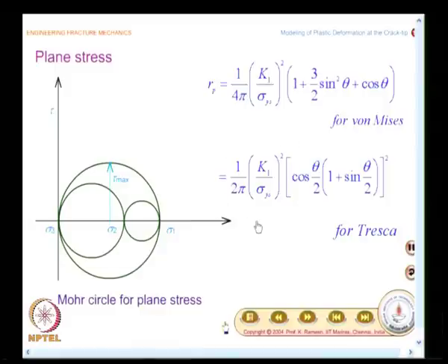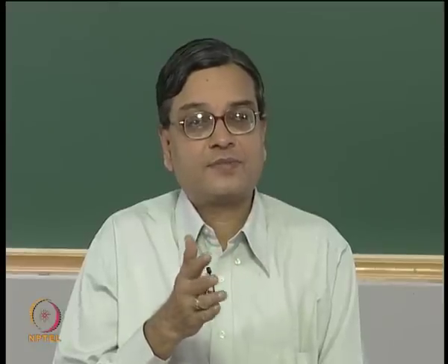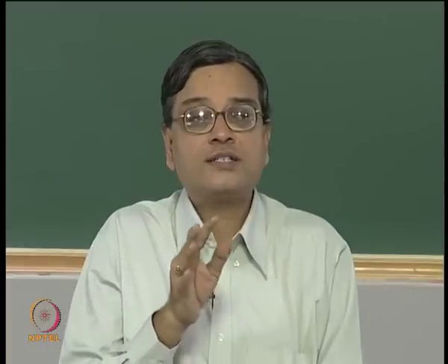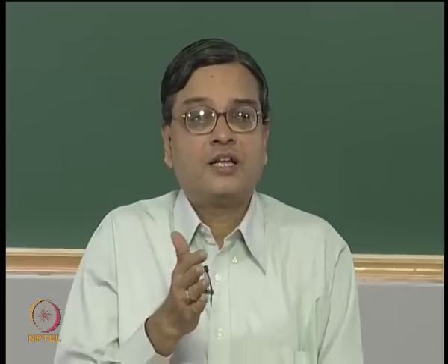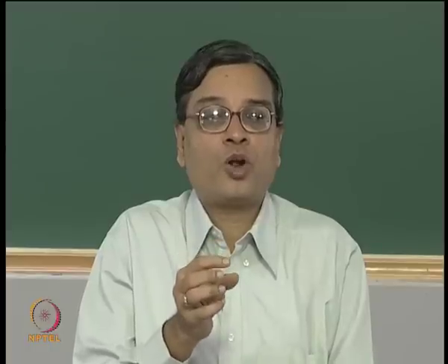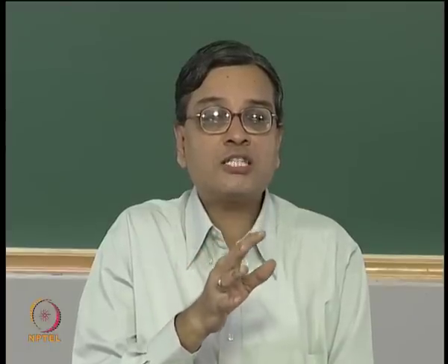So, what I would appreciate is you make an attempt, you go to your rooms, you have the expression, you calculate for a few values of theta, how this shape looks like, and in the next class we will see. And what I would also appreciate is, we have developed this for the mode 1 situation, get similar expressions for mode 2 as well as mode 3 and try to come up with polar plots of the approximate shape of the plastic zone.